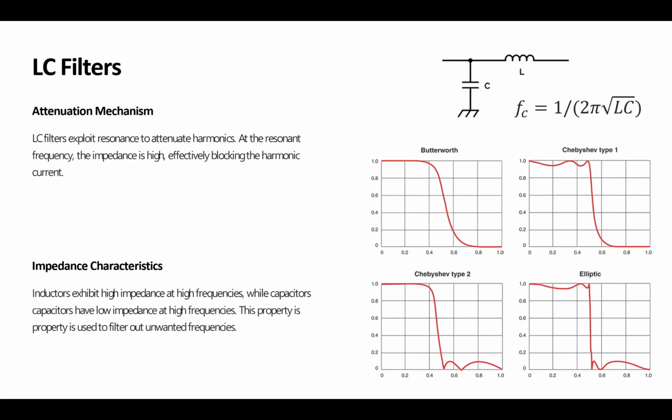The inductor and the capacitance both are differential or integral components. For an inductor, you already know voltage is equal to L di/dt, so it's a differential. And C is an integral component, so voltage is 1 over C integral of current dt. Now you have both of them.